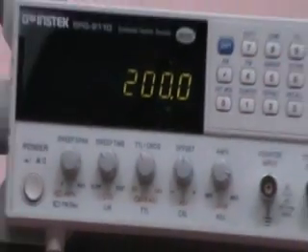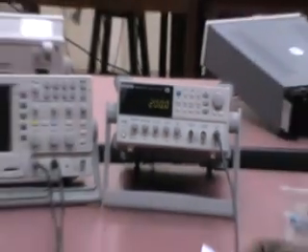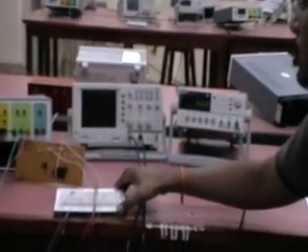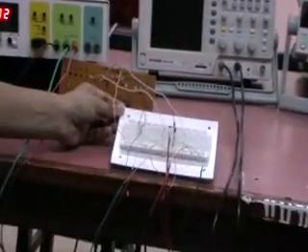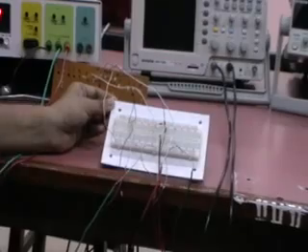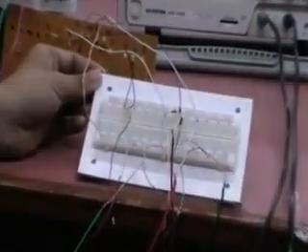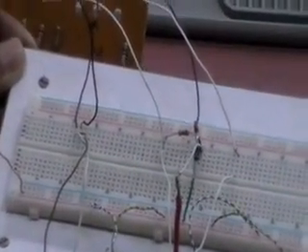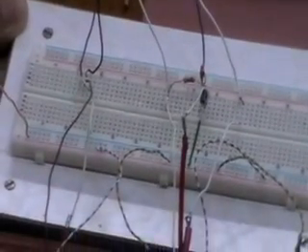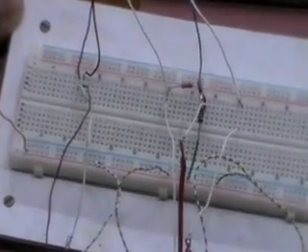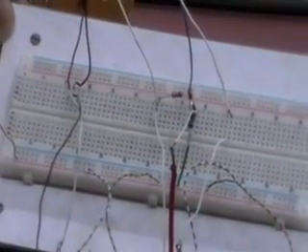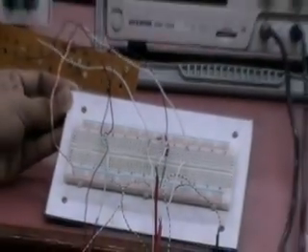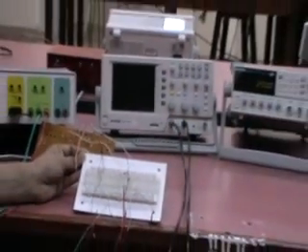So by switching on the DSO, the interconnections are done according to the diagram that is given. As you can see, the Q input is given across the resistor, and the P input is given across the diode. So the differential output will be the difference of both Q and P. So by keeping XY mode, we can observe the IV characteristics. So now to observe the IV characteristics, first we should switch on the DSO.